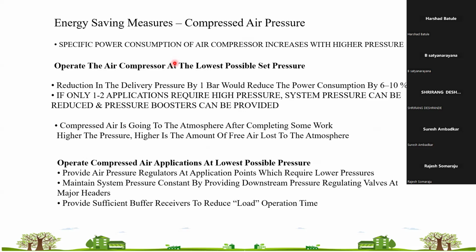Are these filters PM10 or PM2.5? No, those are regular pre-filters. PM2.5 and PM10 are majorly in HVAC for comfort air conditioning. Those filters have a higher pressure drop, and in a compressed air system, a pressure drop means your input power is on the higher side.